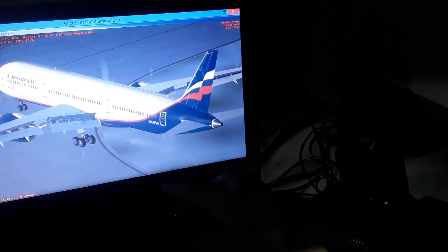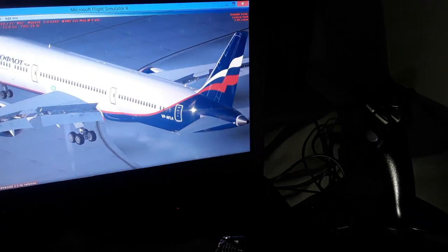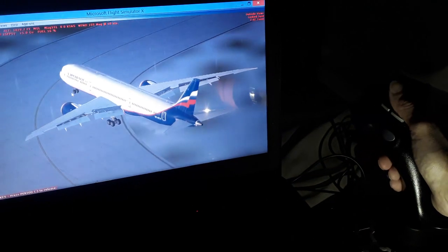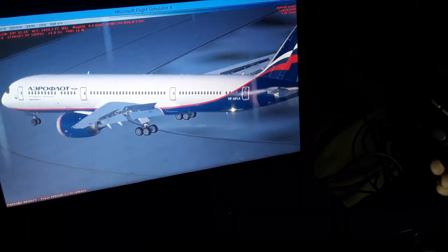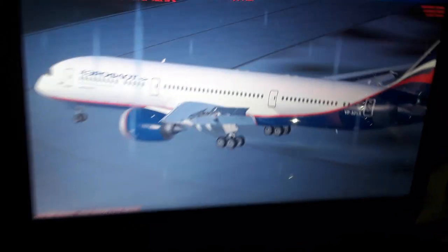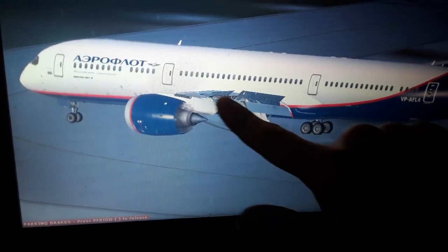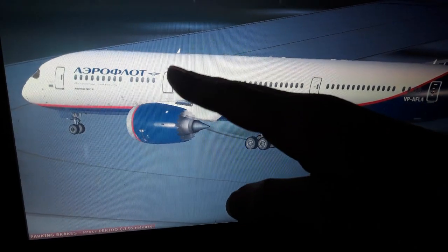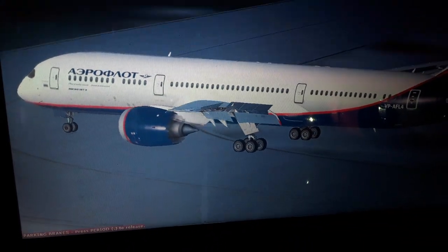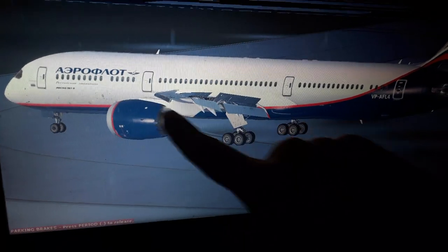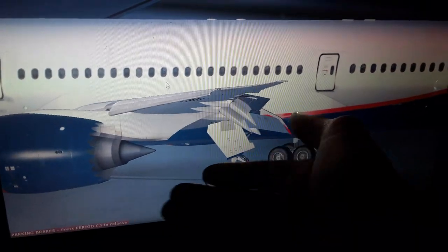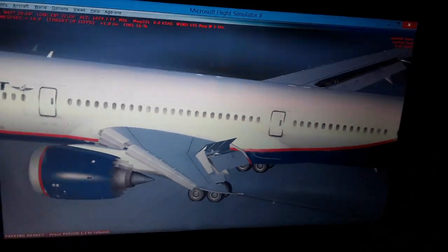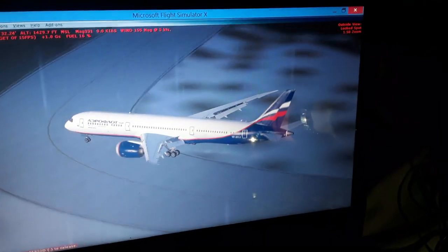So I will show you a couple more things now for the flight controls. So you can see we have also the wings of the aircraft that produce aerodynamic effects, and the flight control surfaces. You can see the bottom surface of the wings is more flat. We have also the flaps extended, and when we fly, the aircraft can have a positive angle of attack. So using the Bernoulli theory of fluids, the airflow moves slower below the wings. So there is higher pressure below the wings, which pushes the aircraft wings up into the air against the weight of the aircraft, through the thrust from the engines that move it forward.